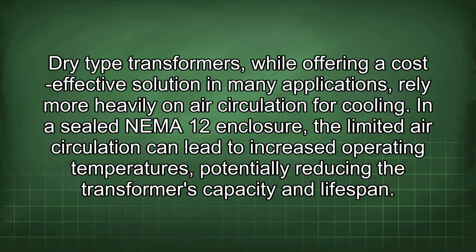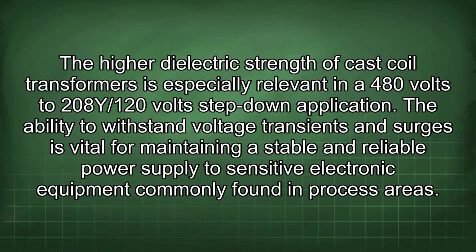Dry-type transformers, while offering a cost-effective solution in many applications, rely more heavily on air circulation for cooling. In a sealed M12 enclosure, the limited air circulation can lead to increased operating temperatures, potentially reducing the transformer's capacity and lifespan. The higher dielectric strength of cast coil transformers is especially relevant in a 480 volts to 208Y/120 volts